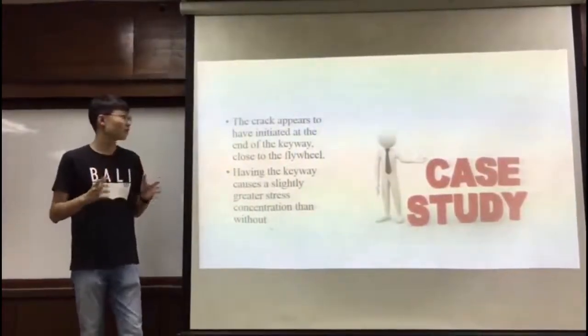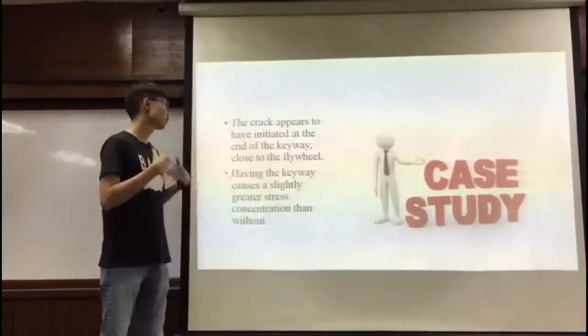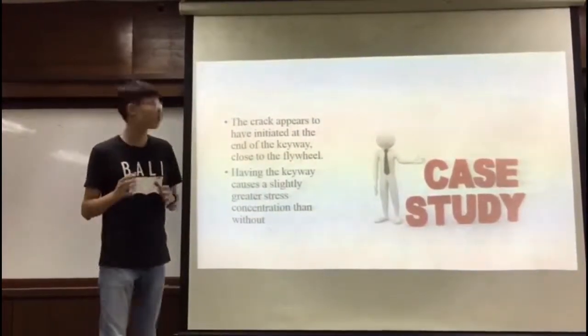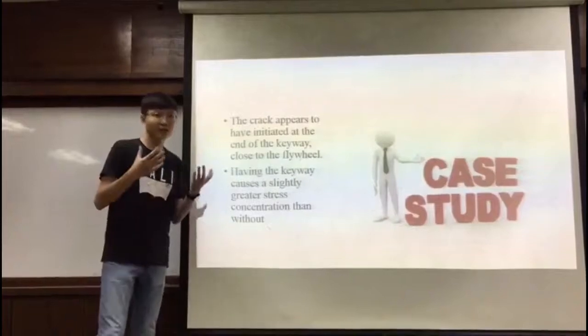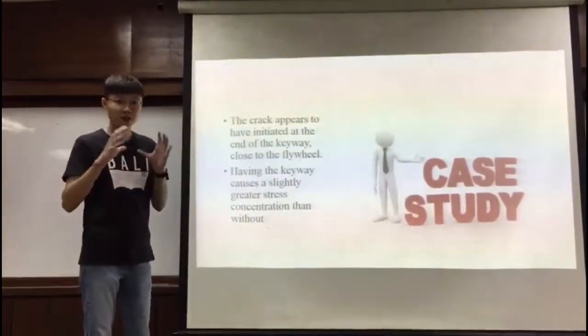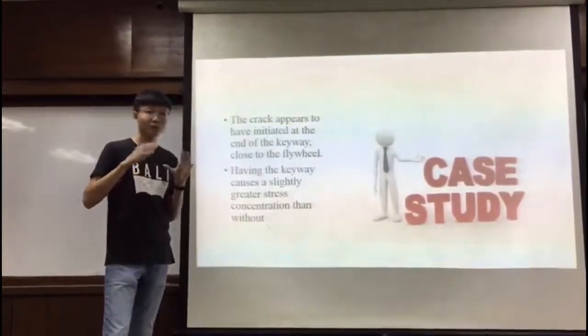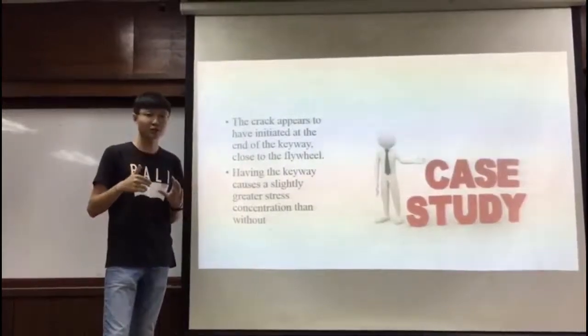Before the failure, cracks appear to have initiated at the end of the keyway close to the flywheel. Having the keyway causes a greater stress concentration at that point, which causes the failure to occur.